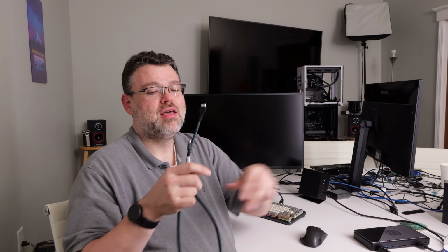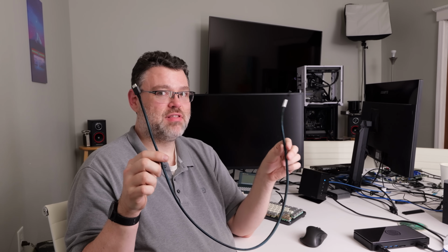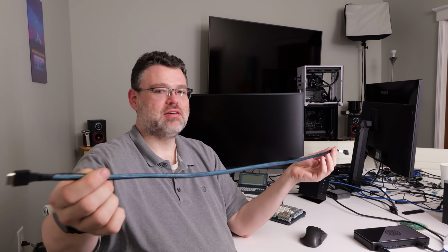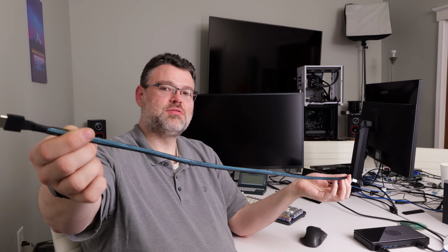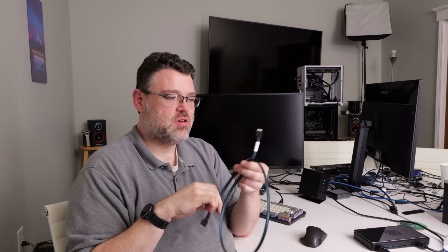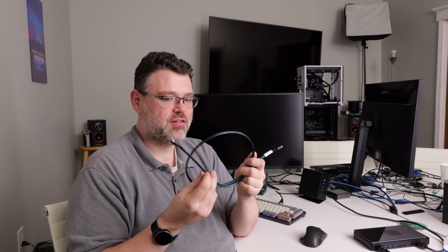And this length of cable, quite frankly, is a problem for PCIe Gen 4 signaling speeds. Even though GPD designed the redrivers on the side of this to be able to deal with this long of a cable, most of the time it's really borderline. You want to use a cable that's about half this length. So this is 100 centimeters? You really want to use a 50 centimeter Gen 4 rated Oculink cable.